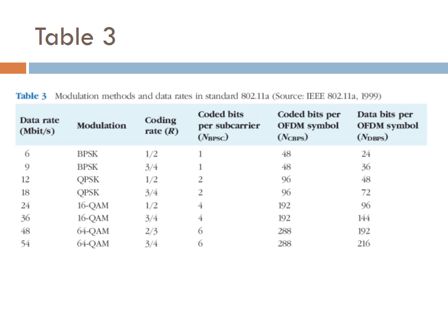Look now at column 3, the coding rate. The data in this column relates to the convolutional coding used to encode the data. Convolutional coding adds extra bits to the data to enable errors to be corrected by the receiver. One way of thinking of coding is as replacing a string of data x bits long with longer strings y bits long.